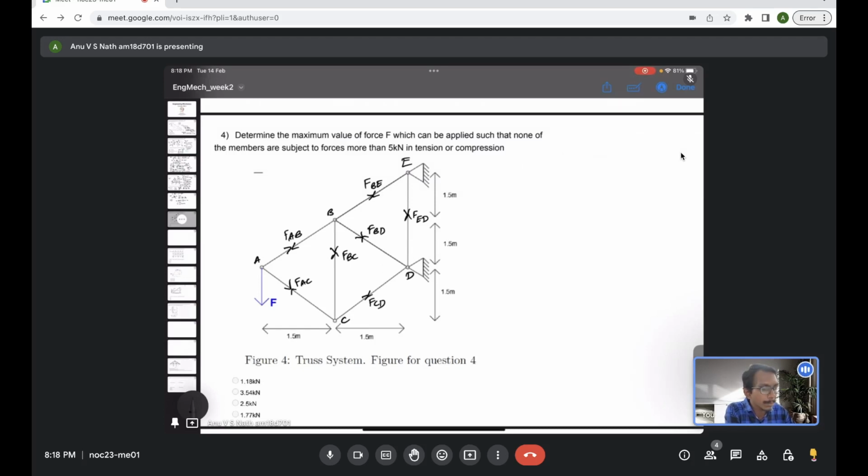So right now we have supports at E and D, both are pin joints. There's an issue because now it is over-constrained, in the sense that we have four unknown reaction forces, which with the three equations we cannot solve all of them. So there's an issue with the support reactions. For the moment we will just forget about it. We'll come to that. Right now we don't need that to solve this problem. We only need the internal forces. We don't need support forces.